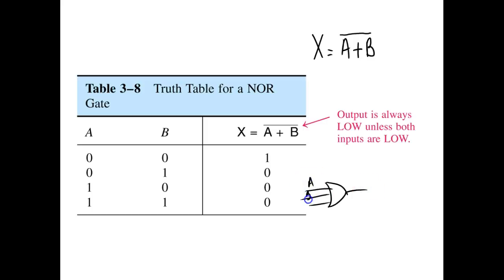We'll call this A, B, C, and we would call the output Z. So what would it be, guys? Z equals A or B or C, with a bar across all three of them. Yeah, it has to go all across. Don't stop.